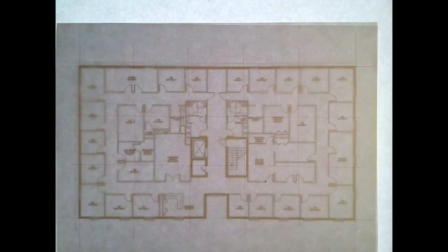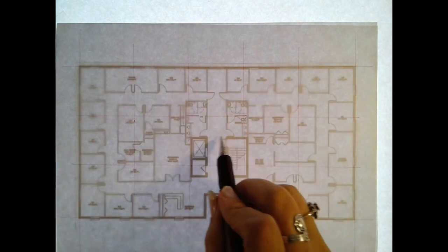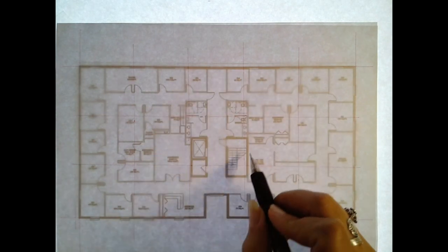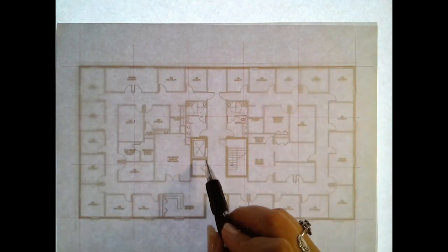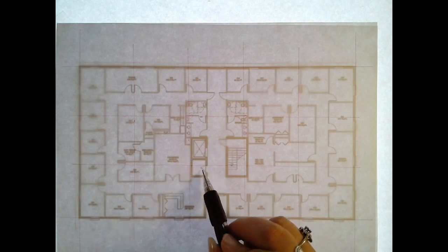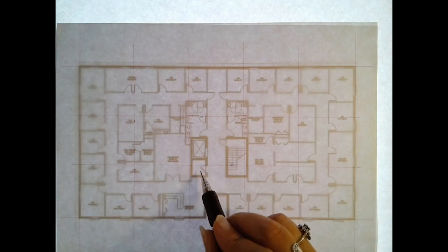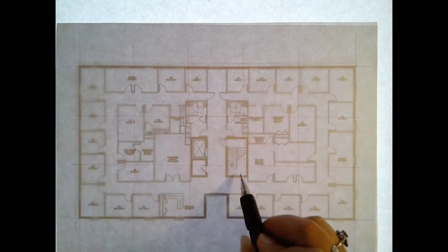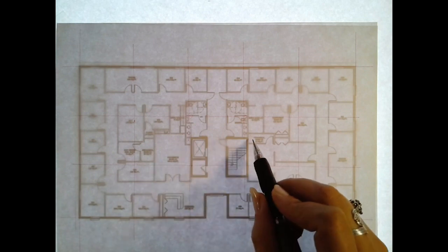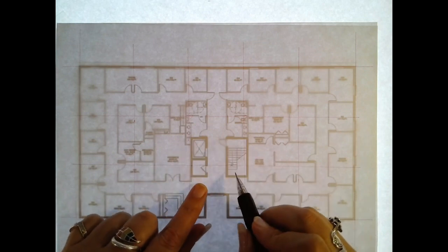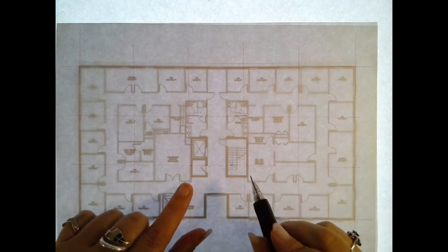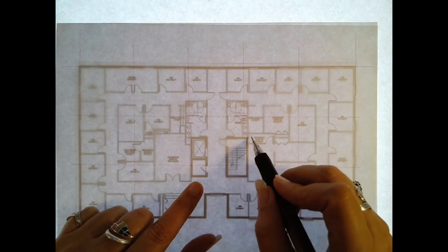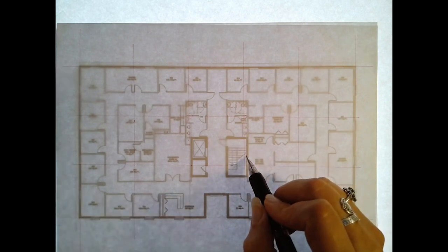In buildings of this nature, kind of a rectilinear plan with a core in the middle, the core is often a controlling element. Things work out from there. So we have a stairwell, we have an elevator shaft, probably a mechanical equipment closet at every floor level, and then the bathroom. So this whole thing kind of defines the core, and certainly the stair and elevator where there are heavy walls that are probably shear walls for lateral stability. So it's ideal if I could actually get into those walls.